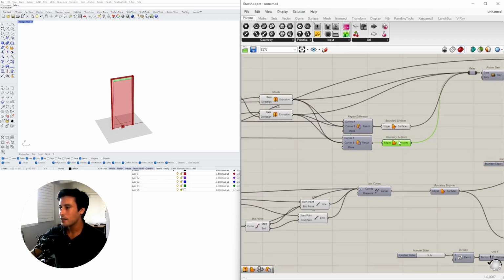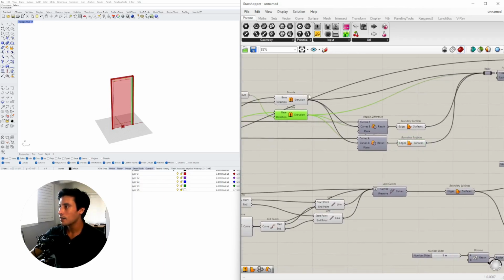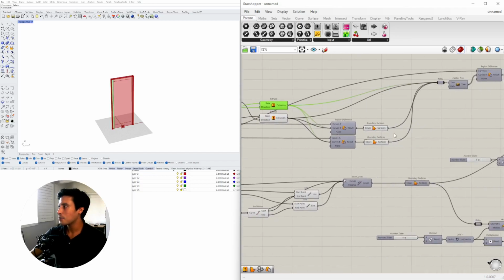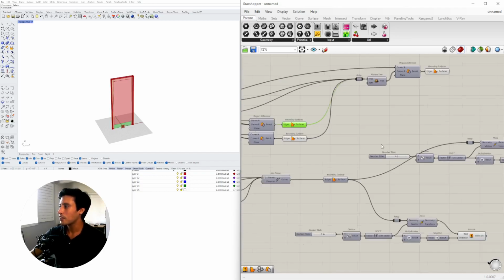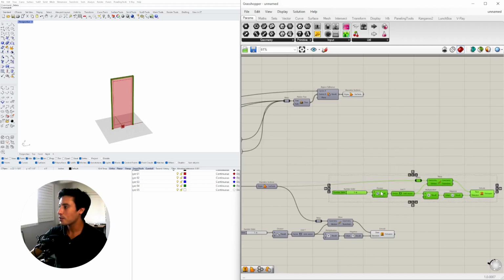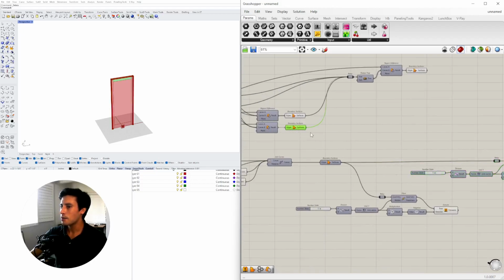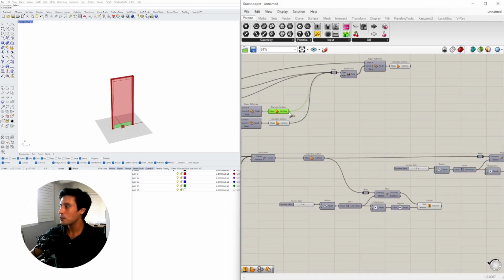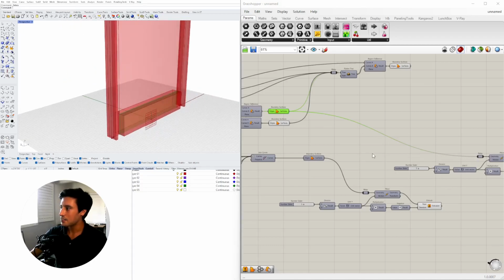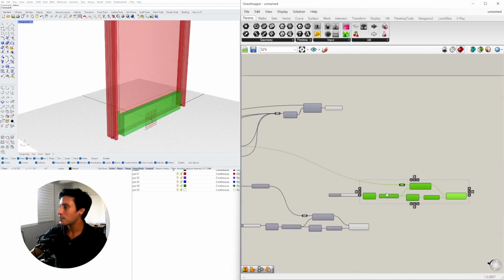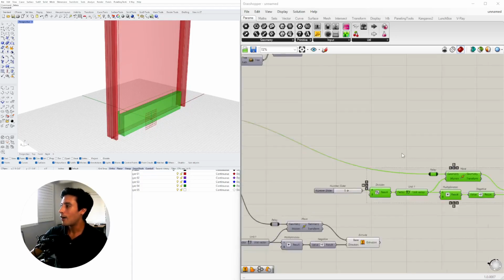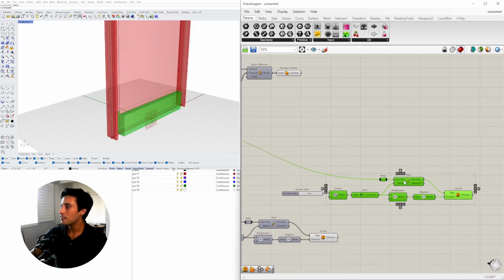Now we are here where we can start with our design. So we want to start with the bottom rail. Honestly, it doesn't matter which ones you start with. I just think that sometimes if I do the bottom one here, it already has that thickness. And if I want it to be the same depth for all of them, I'll copy everything except for the slider.